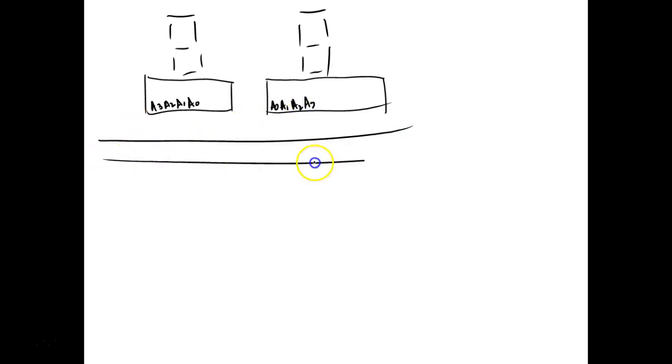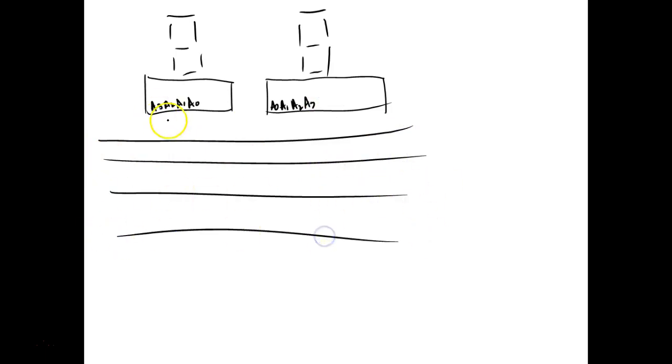What we would have is 4 data bits coming down here, and then they would hook up like this. And this one right here would hook up to the same data lines. And then each one of them would use this ripple blanking input.